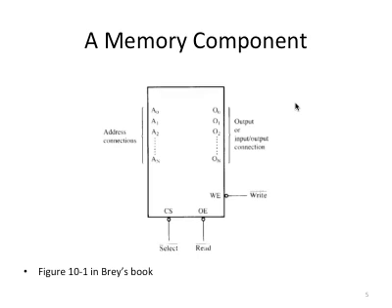At the bottom of this chip, you see there are two control signals, CS and OE. CS stands for chip select. OE stands for output enable. Chip select is oftentimes active low, which means that if you want this chip to work, you need to put a logic 0 on CS. OE is for outputting.